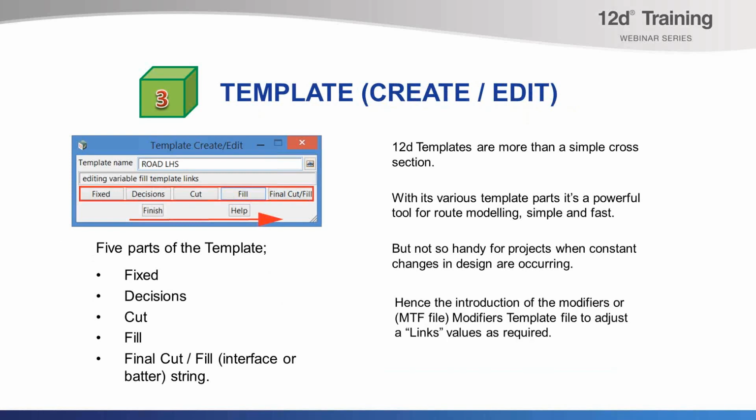The only problem we get into is that if you actually want to modify the links or change them, if the roads get wider or narrower or change in super elevation, then this is where the templates are sort of too fixed in place, and that's why the modifiers, or the MTF file, the modifiers template file, was introduced to then go and adjust the links as we need to.